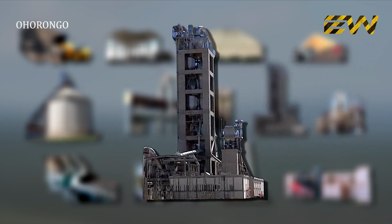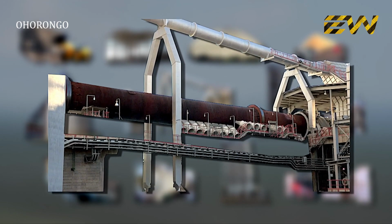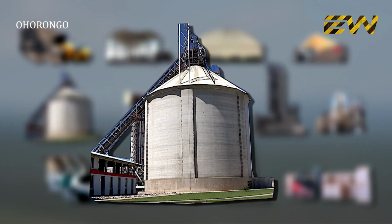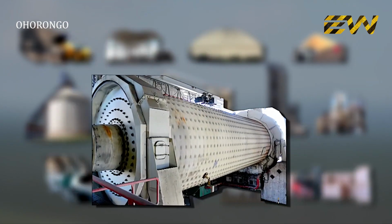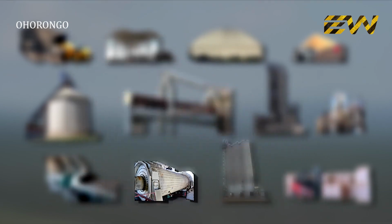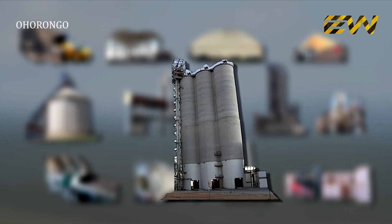Now the raw mix is transferred to the preheater. Here the material is preheated, after which it enters the rotary kiln, where it's burned to produce clinker. The clinker is cooled down with air in a grate cooler and then stored in the clinker silo. Additives such as gypsum and limestone are added to the clinker before being milled in the cement mills to the final cement product. The cement powder is stored in the cement silos. From here, the final stage is the bagging or bulk dispatch of the cement.